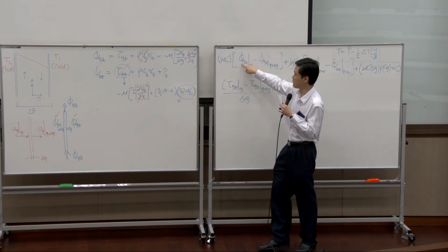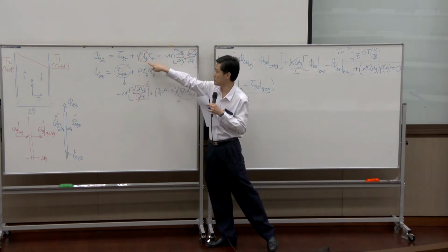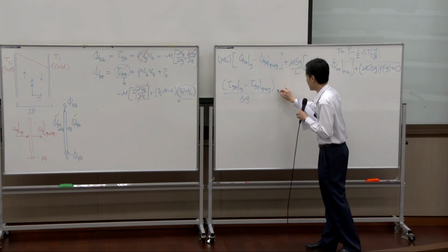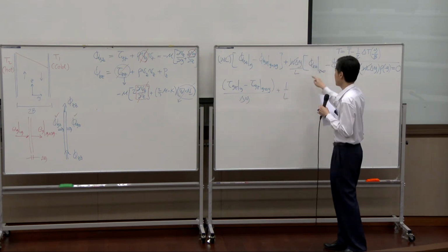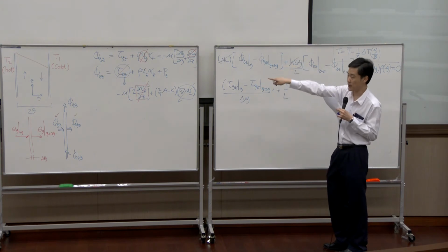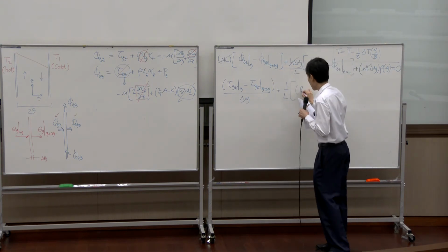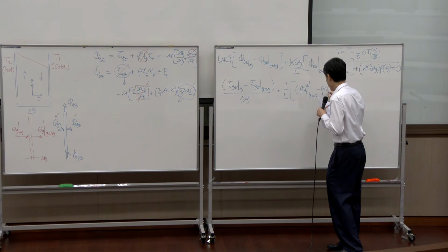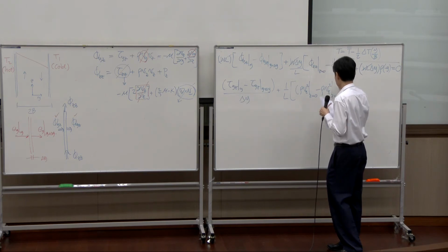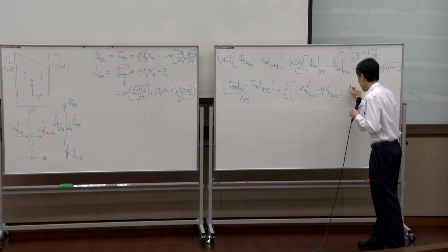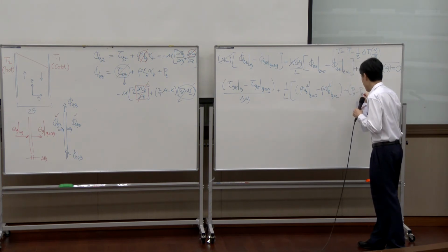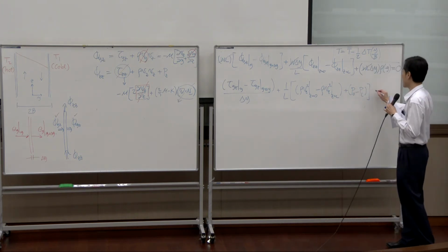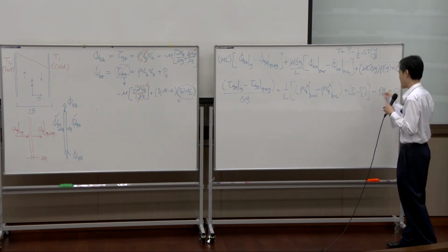We determined earlier that phi is basically tau because Vy here is 0. So plug it back here. This term, we have 1 over L. This term turns to be rho VZ squared only. So inside you have rho VZ squared at Z equal to 0 subtracted by rho VZ squared at Z equal to L, plus the pressure difference term P0 minus PL, minus rho g equal to 0.